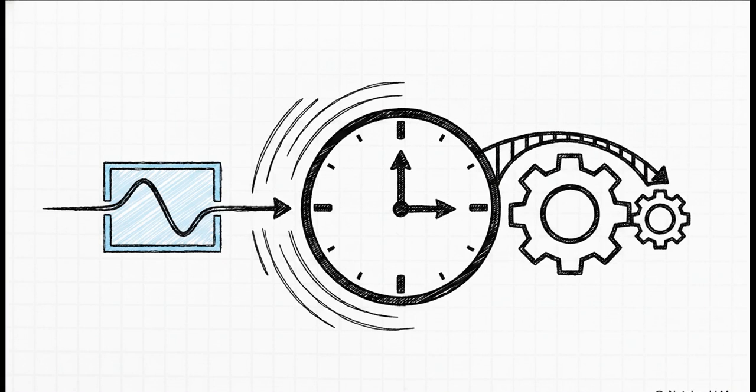We're talking evaluating synchronous versus asynchronous resets and performing really rigorous setup and hold time analysis so your data is perfectly stable before and after a clock edge. It also means you have to safely navigate clock domain crossings, ensuring that incredibly fast and incredibly slow signals can actually talk to each other without completely corrupting your data.